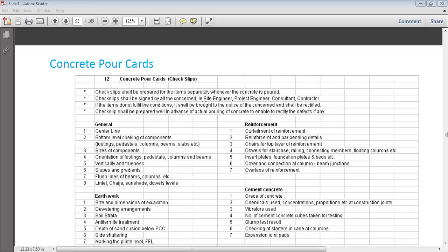Okay. Sand cushion is required where we have very cohesive soil, in short, where the soil has some flexibility, like black cotton soil. When you take it in your hand you get a smooth feeling, and you feel that after pouring water it can swell, it can contain water, and if any load is applied, definitely it will settle down. So for cohesive soils, we require that sand cushion.